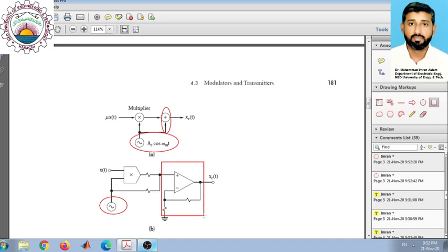So this is the circuit of an operational amplifier in addition configuration. You can see that this op amp would be adding this signal which is coming out of this product and this cos omega t. So this operational amplifier performs the function of addition here, whereas we need additional circuitry to perform this multiplication, which is represented by this block here. You can see that this block with a cross sign is used to represent a circuit which is used for multiplication.